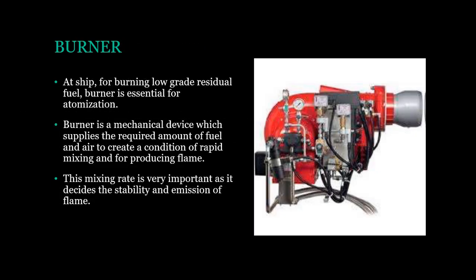At ship, for burning low-grade residual fuel, burner is essential for atomization. Burner is a mechanical device which supplies the required amount of fuel and air to create a condition of rapid mixing and for producing flame. This mixing rate is very important as it decides the stability and emission of flame.